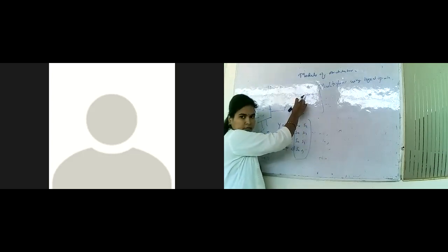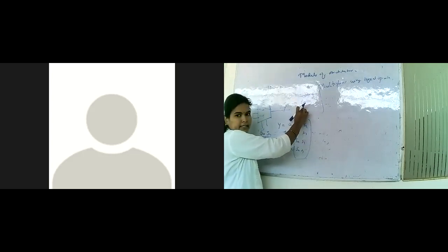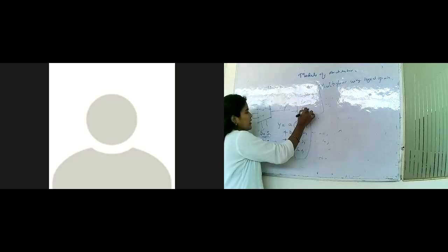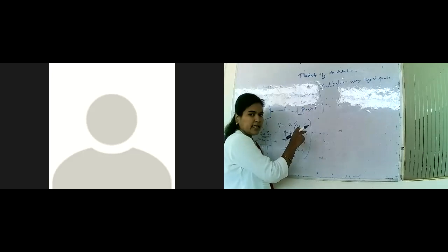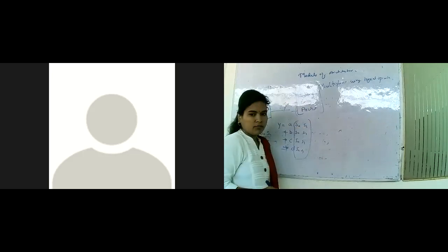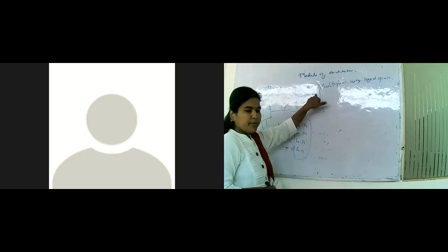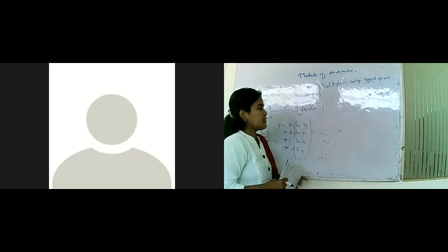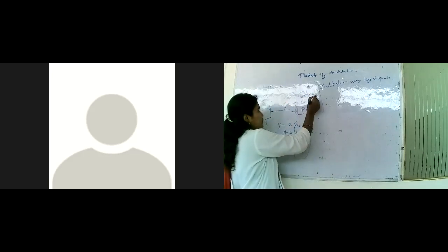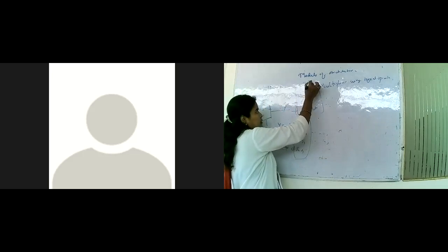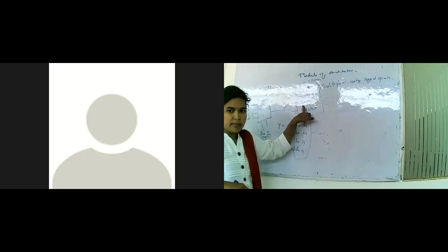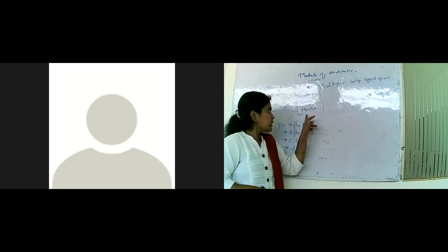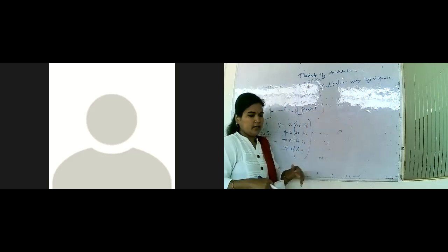See here, library is the first thing. The second one is entity, and the third thing is architecture. These are the three sections of the program. In the library section, you have two lines. To represent the library, you use library and use, which I explained. Next, in the entity, you explain the inputs and the output. In the architecture, you explain the design.